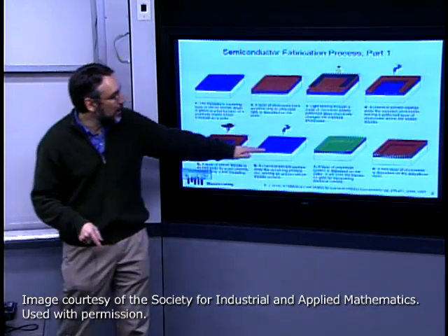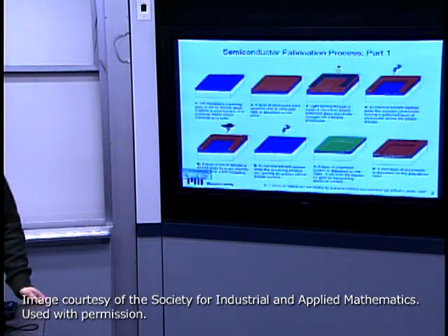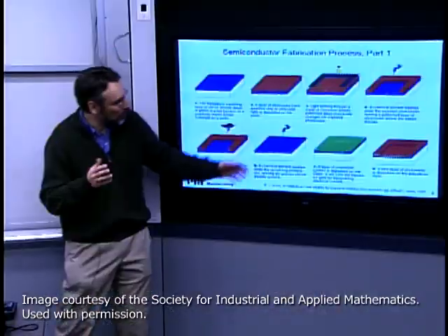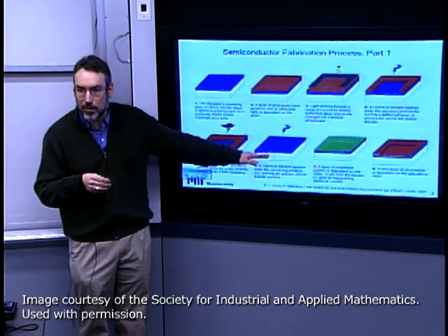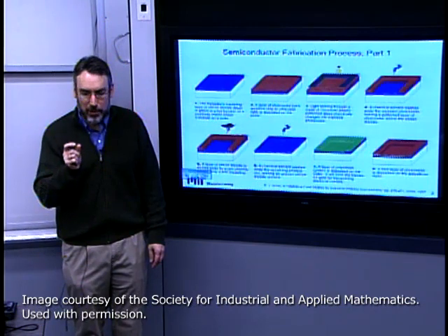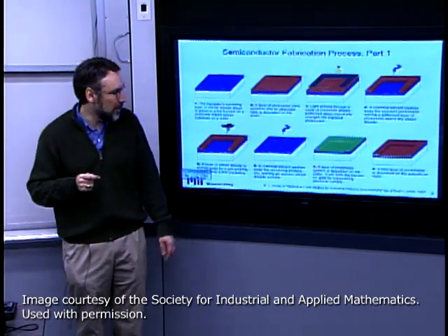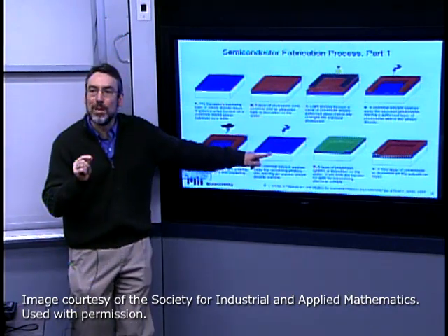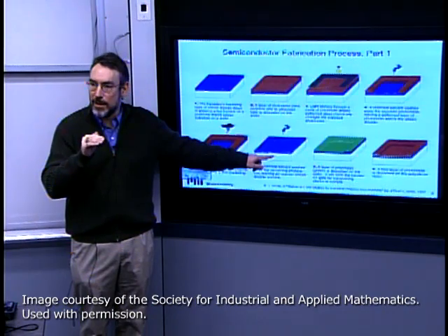Then I can go back in, and with different process conditions, lower temperatures, more pure chemicals, or even using alternative process technologies that involve very, very short time oxidations, rapid thermal oxidations, I can now controllably grow 1,000 angstroms or 100 angstroms or whatever I need.